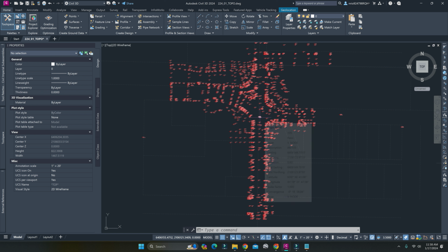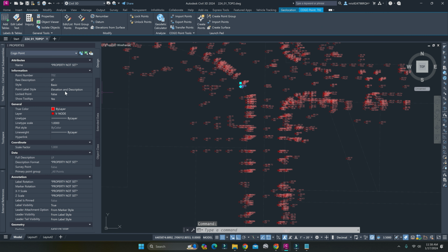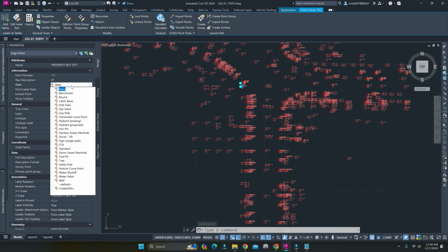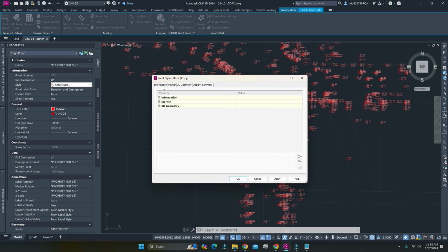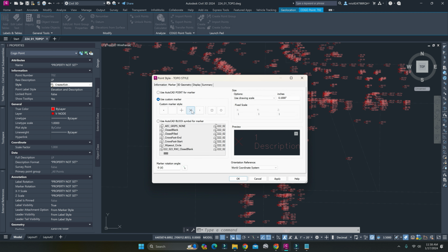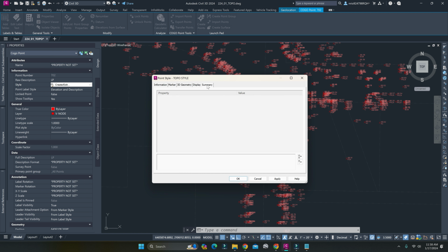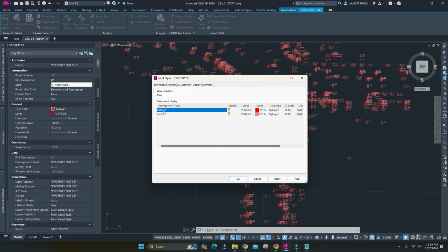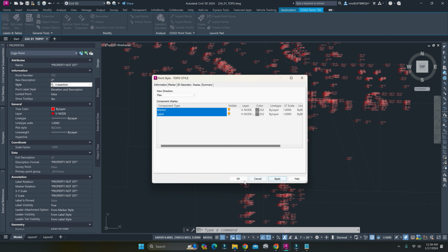First we should take care of our points for the survey. So we're going to select this point. And here we'll see basic elevation description. We're just going to go to create new and copy current selection. Go to information over here and go topo style. Yeah, we want X display. Here we're just gonna select these two. We're just gonna hit the 252, which is always what we do.